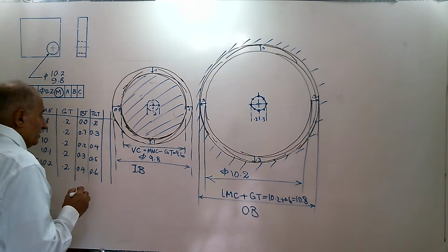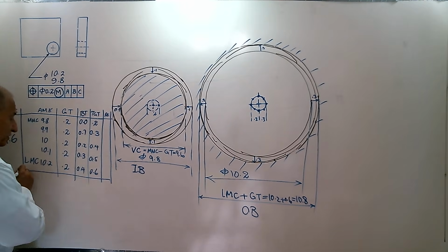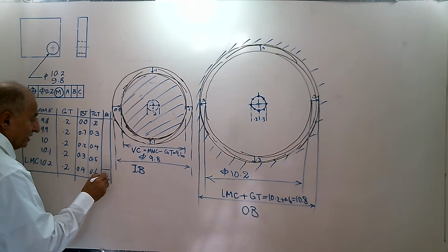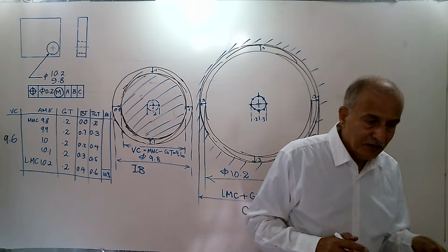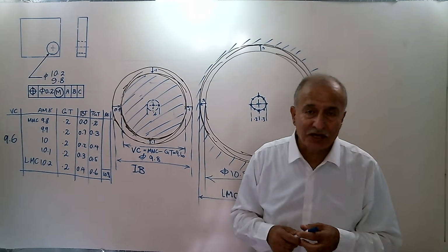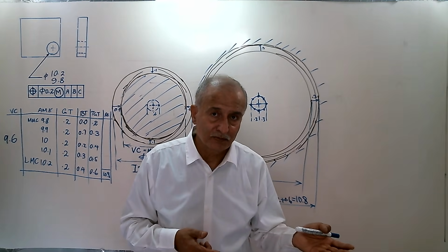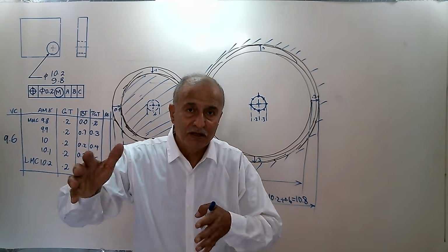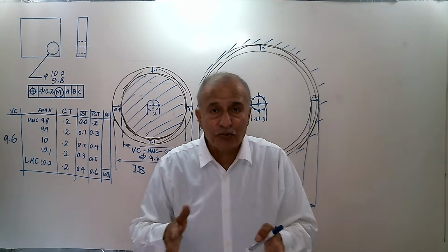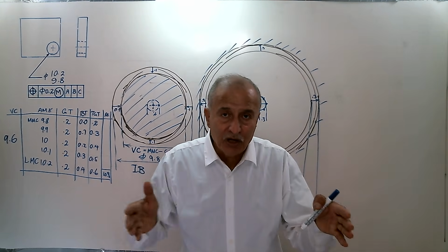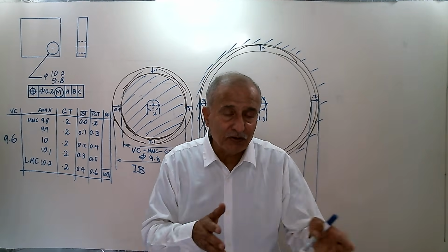Then here, you can write RC conditions belong only to this size, 10.8. The same story here. The region between 9.6 and 10.8 is a keep-out region for the hole. The hole can be shifted depending on the size, approaching 10.8 or approaching 9.6. It can be between them.